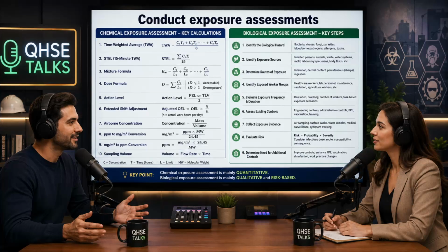By multiplying them together. Right, you multiply the protection factor by the chemical's PEL. So 50 multiplied by the 0.1 fiber PEL gives us an MUC of 5.0 fibers per cubic centimeter. That is the hard mathematical ceiling for that specific piece of equipment. If your air sampling shows that the ambient concentration of asbestos in the room is 6.0 fibers per cc, that full-face respirator is legally and mathematically insufficient to protect the worker. It's failing them. You must upgrade them to a powered air purifying respirator, a PAPR, or a supplied air system, which carry much higher APFs of 1,000 or 10,000.